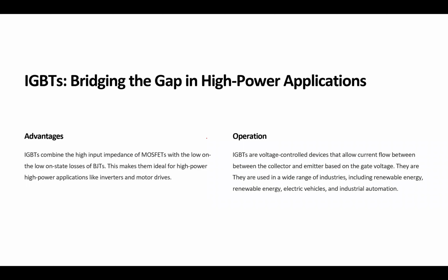So losses in a MOSFET are higher. What does it mean when we say higher losses in a MOSFET compared to an IGBT or BJT? Less efficient, but what is the immediate impact of having a power loss? Heat. You remember it was one of our challenges, or the sensitivities of the power electronic component. So a MOSFET has a bigger problem with heat than an IGBT or BJT.